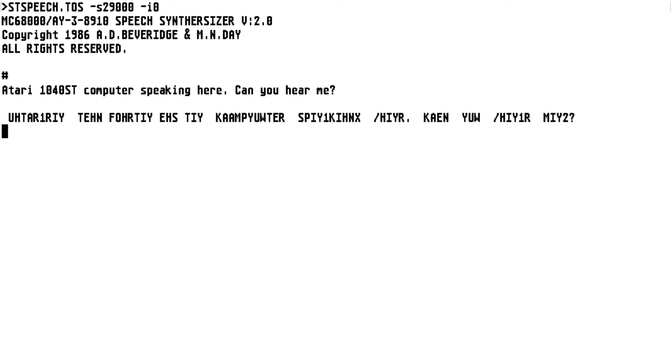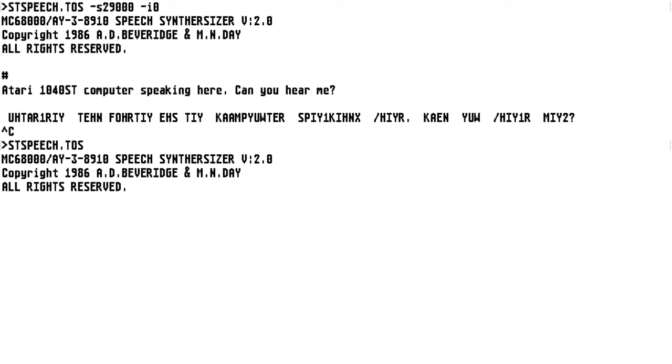like 7 years ago, and I released it, but people were kind of unhappy. They said, well, it doesn't sound right. Although I said, well, I made everything sound right. I even increased the sample rate. Until I figured out, well, the output stage, the converter was running at like 8 kilohertz, and there was really no proper oversampling. So the DAC had horrible aliasing, but it was part of the sound.